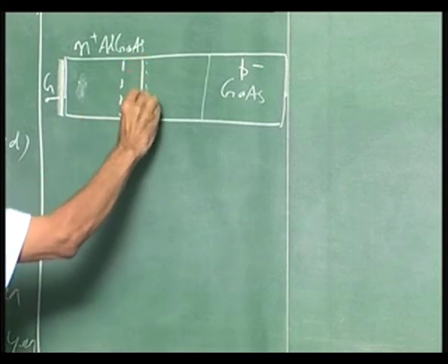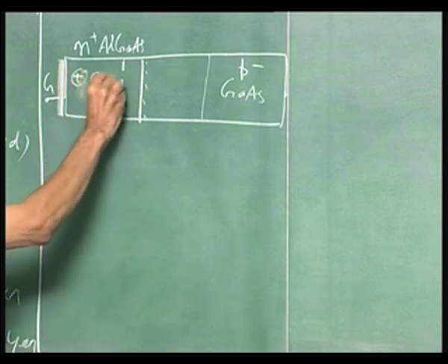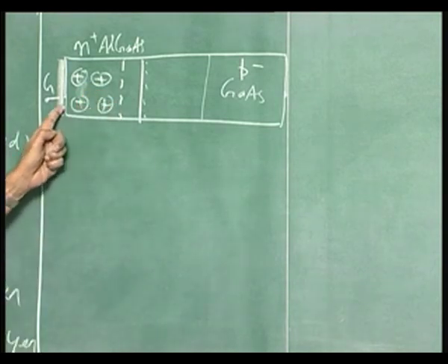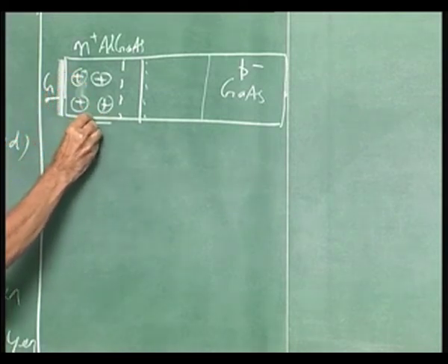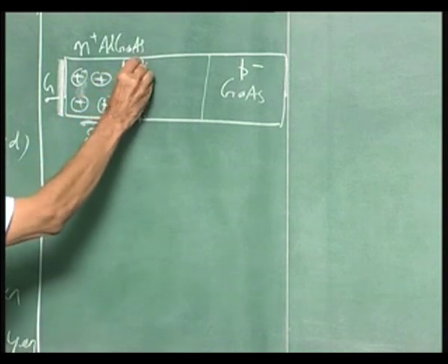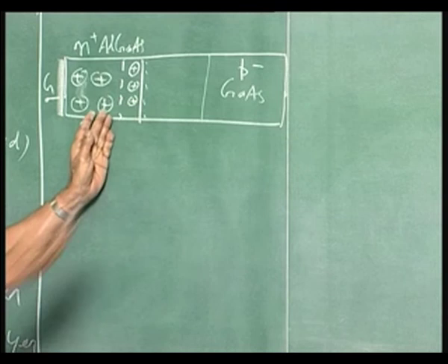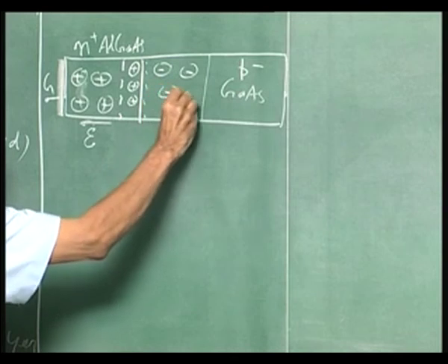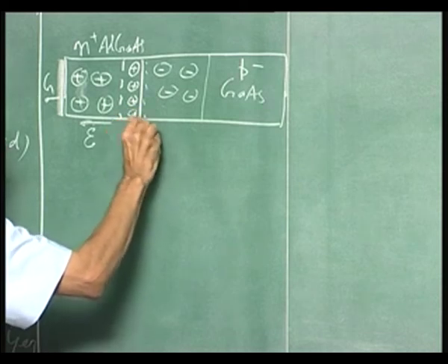And there is a depletion layer here. There are plus charges here. These plus charges belong to the depletion layer of the Schottky barrier. They are moving field lines in this direction here. That is the electric field direction. These charges here belong to the junction, and those field lines are here, okay, E1, E2.